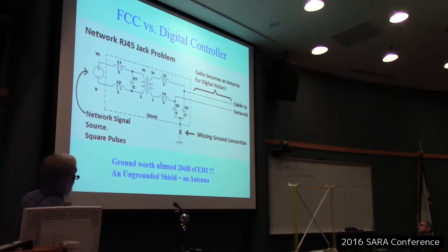And I thought, okay, you get good enough pay. So anyway, upon investigating it, the whole network cable had turned into an antenna because there was a missing ground. There's this little box, which I'm guessing what's in it, that coupled between the network chip and the network connector that plugged in there, and there wasn't a ground right here. And the EMI dropped down, with a near field probe and a spectrum analyzer, by about 20 dB.